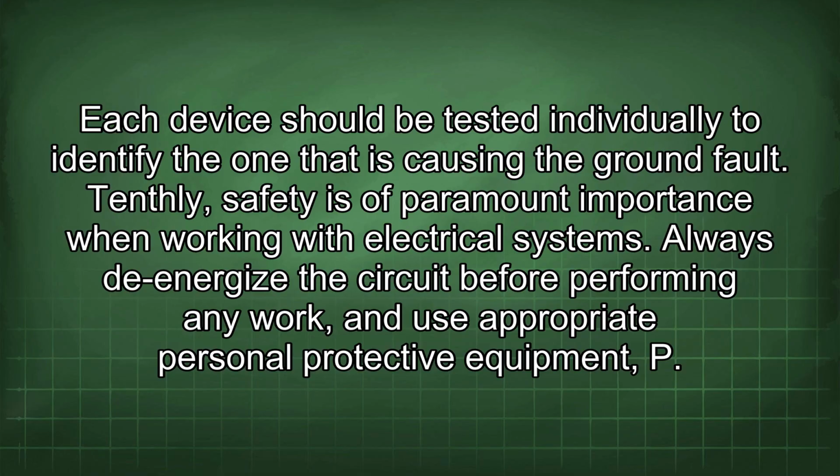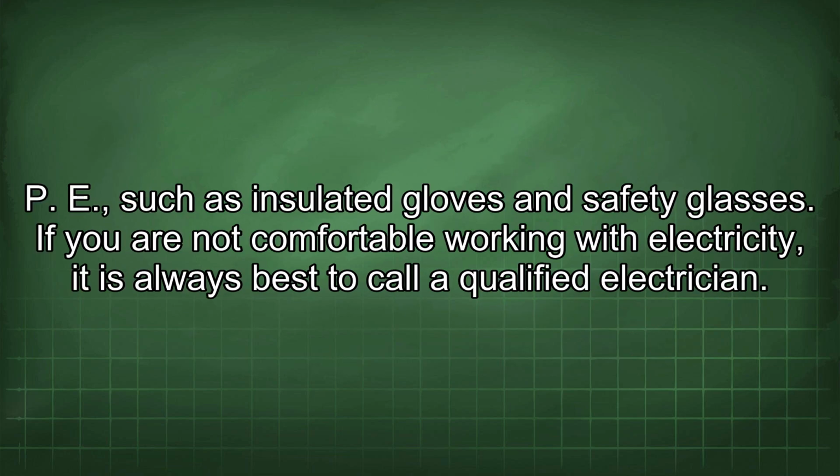Always de-energize the circuit before performing any work and use appropriate personal protective equipment (PPE), such as insulated gloves and safety glasses. If you are not comfortable working with electricity, it is always best to call a qualified electrician.